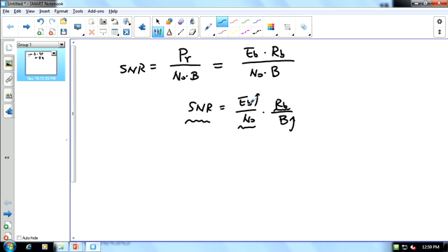Because we are transmitting redundancies, the total energy will be bigger, and the total information bits remain unchanged. Therefore, equivalently, we are allocating more energy to each information bit, which means E_B over N naught becomes bigger.